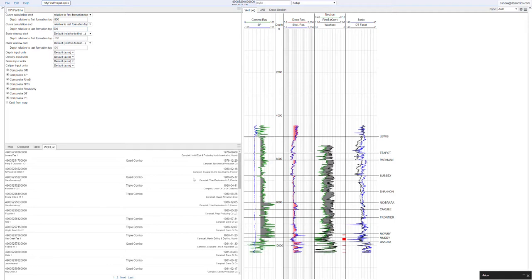Okay, and then we have our statistics window. The statistics window is important. It is more than just aesthetic. What the statistics window does is it says, I'm going to come in here to a defined interval range, and I'm going to start pulling statistics such as the median, the P50, the P10, the P90 from your data, and I'm going to use that to help build up this interpretational blueprint.